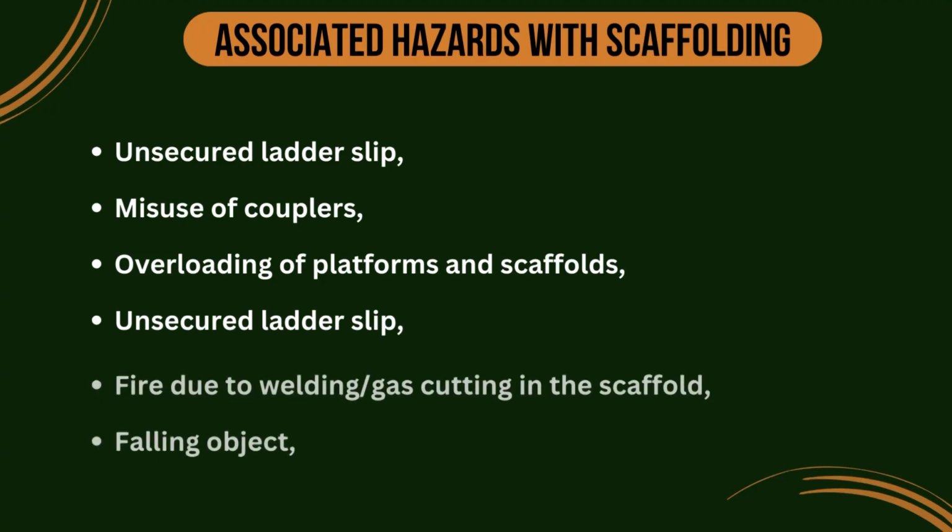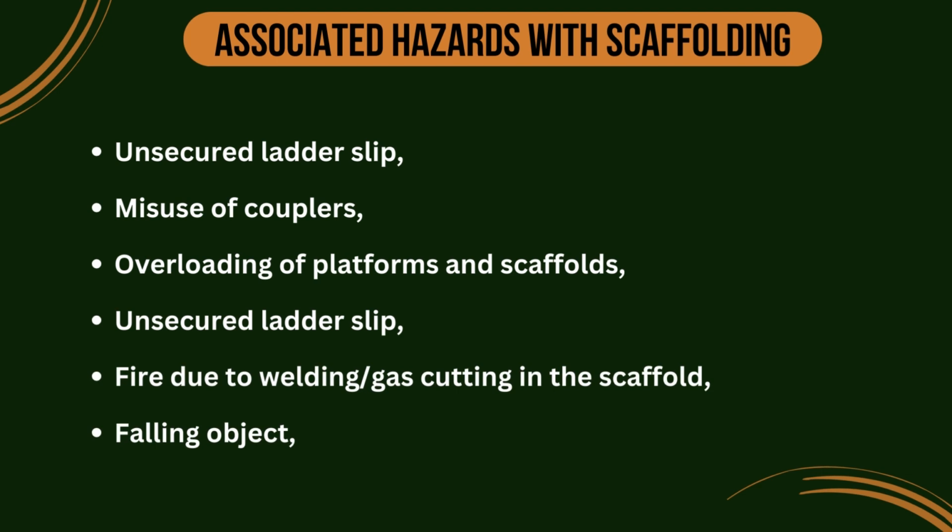Then fire due to welding or gas cutting in the scaffold. At times we find that some member is longer than our requirement, so what we do is welding or gas cutting. While doing this gas cutting or welding, we have to be very careful, otherwise because of the flames there may be a chance of a fire accident.